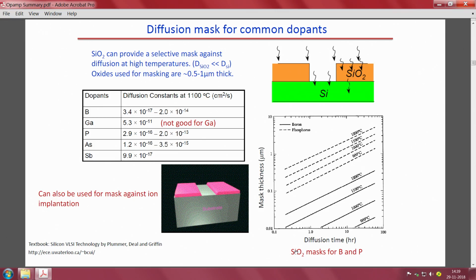Further, if I also want to dope the wafer, in a similar way to etching the silicon wafer, instead I want to dope the silicon wafer only in this region. Then using lithography, if I protect these two areas and I dope it, my dopant will only reach this particular region of the silicon wafer. So, this is just a silicon substrate, and silicon dioxide is shown in pink color. If I dope it, it will dope in the substrate.